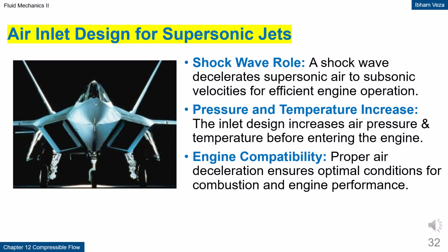Air inlet design for supersonic jets. In supersonic aircraft, the air must be decelerated before entering the compressor. Shock waves are used to reduce the Mach number from supersonic to subsonic. This process also increases the air pressure and temperature. A good inlet design maximizes stagnation pressure recovery. This strongly determines the performance and efficiency of the jet engine.